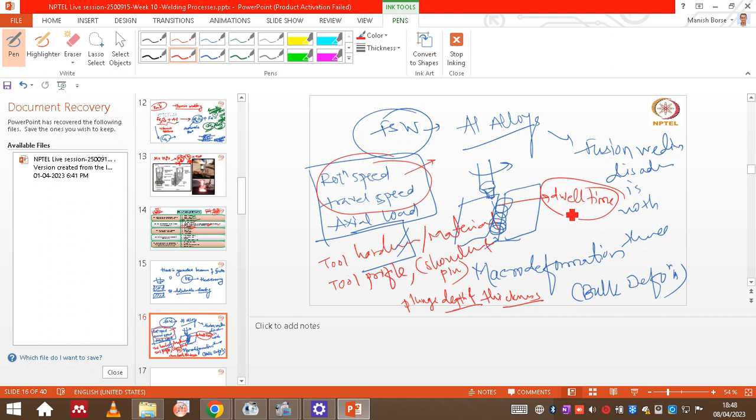Let's say if we want to join steel or titanium, we need more heat at the interfaces at the start, so that the material will be sufficiently softened at the start of the process, and the surrounding material will be preheated, right? Obviously, dwell time in certain cases should be maximum at the start of the process, right? So that will also contribute to the proper softening of the material.